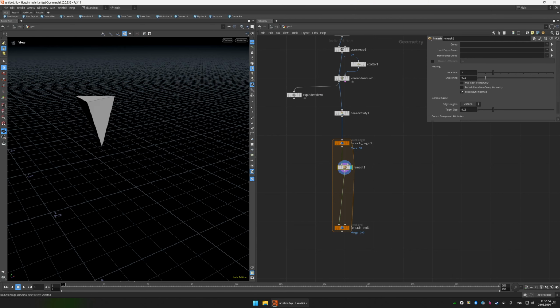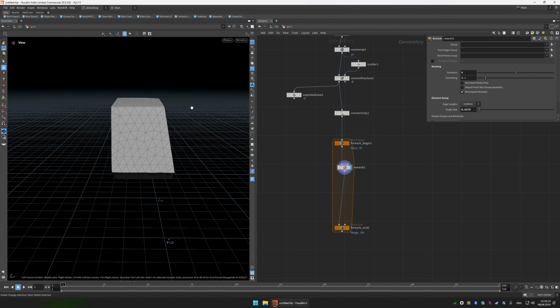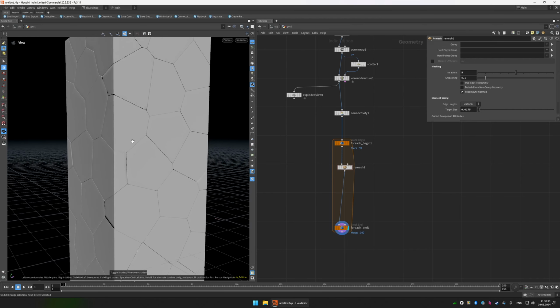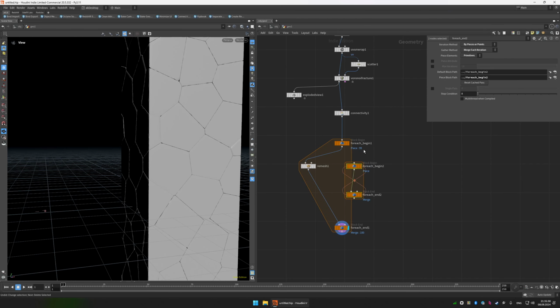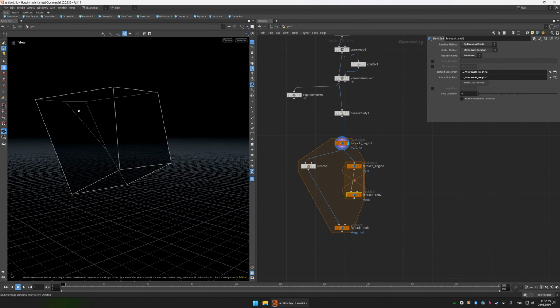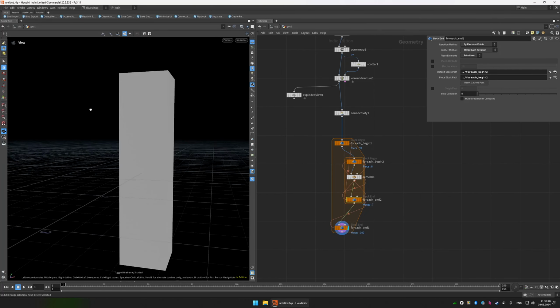Okay, so the remesh, the parameters that I find working is this one, 0.0175. This is good. If you look at the output here, we get one problem because we're remeshing this, we get these weird artifacts here. And the fix that I found is you can actually run another loop over each of those polygons, right? So we select here primitives, which is our polygons in this case, and then we run a for loop. And after you remesh this like this, everything is good.